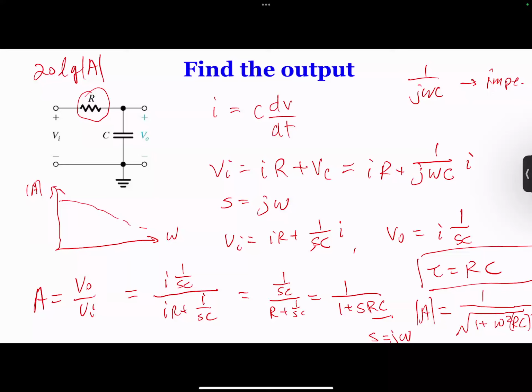And if you have a gain of, say, 10, in this case, you'll have 20 dB of gain, right? Log 10 is 1. So if your gain is 100, you got 40 dB. If your gain is 1,000, it's 60 dB. So every 20 dB means you're increased by 10 times. Now you recall a logarithm plot: every factor of 10 is the same distance, from 0.1 to 1, from 1 to 10, 10 to 100. So they can shrink the gain in a linear plot. That's what this dB can do for you.